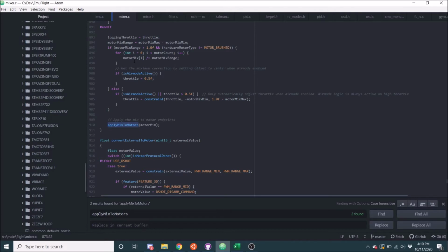And we don't want that. We want all the motors to be scaled between 0 and 1. So what we first do is we find what the range is, and then we divide each of the motors by the range. By dividing them by the range, this gives us all the motor outputs within a range between 0 and 1, because it rescales the range of the motors so that the range is now 1, so that the difference between the max motor and the min motor is 1.